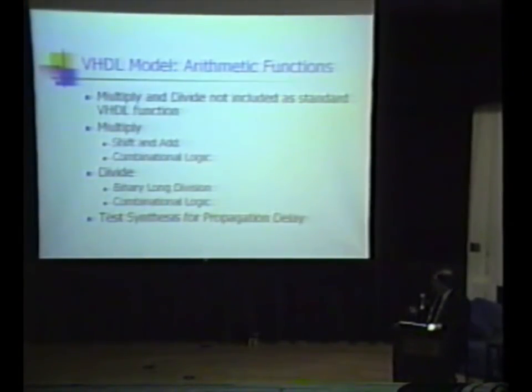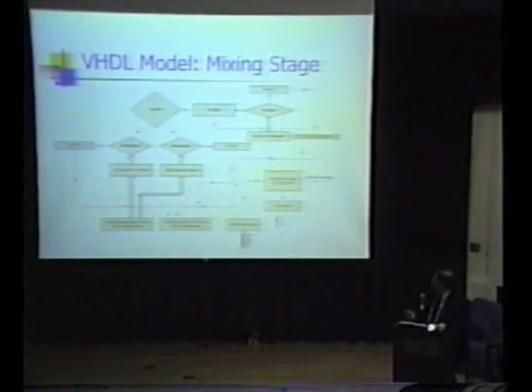Then we needed to do test synthesis for the propagation delay. Propagation delay is important because we need to figure out the best clock frequency for the mixing stage, which is right here. This is the mathematical functions used in the mixer.